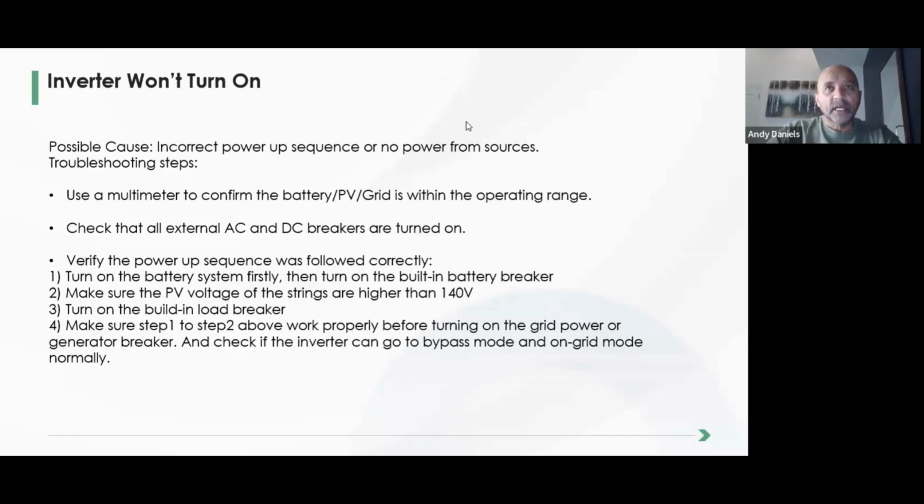The aging section is a temperature-controlled, environmental room where they can lower the temperature to the extreme low, or raise it to the extreme high. Inside this chamber, they put machines back to back, and one machine receives solar and battery and discharges. The output power goes into the machine on the back end as its input power. They run that for 2 hours, and then they switch roles.